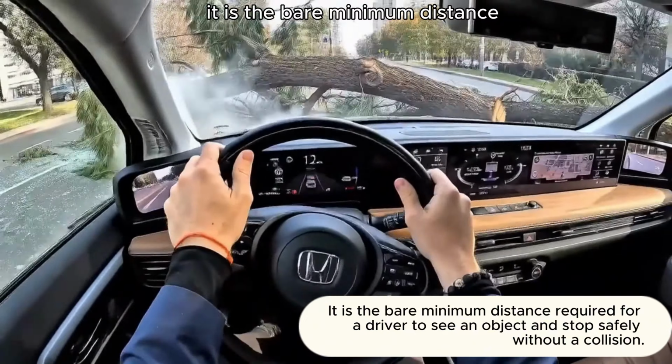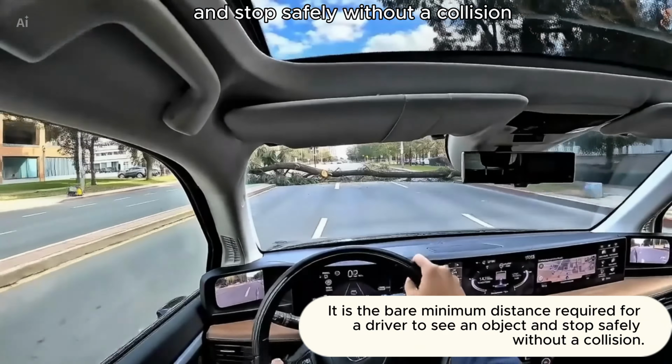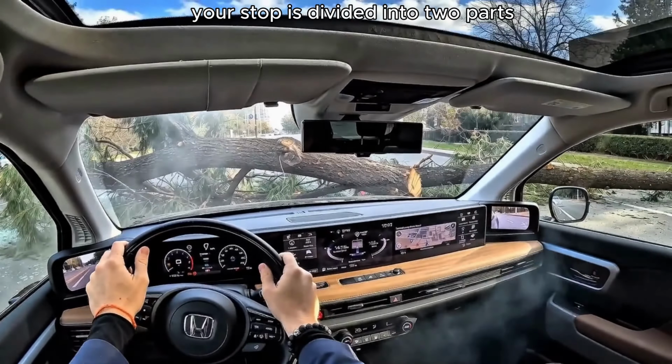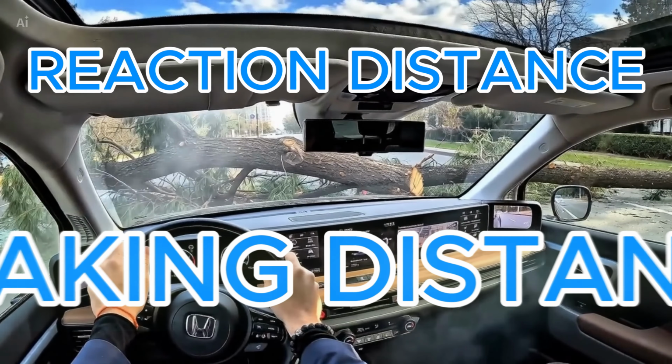It is the bare minimum distance required for a driver to see an object and stop safely without a collision. And it applies to every single road and street ever built. Your stop is divided into two parts, the reaction distance and the braking distance.